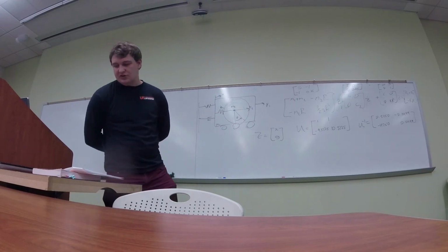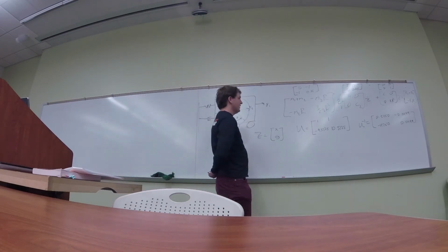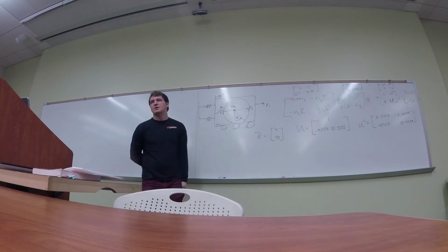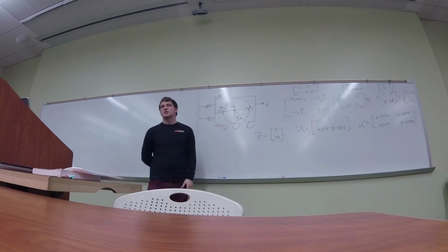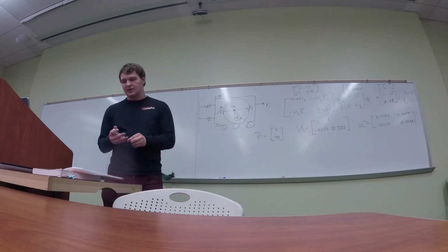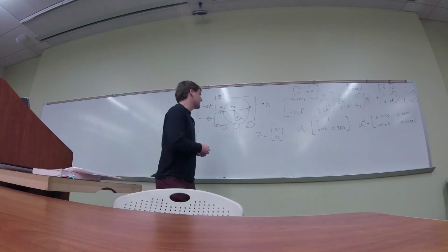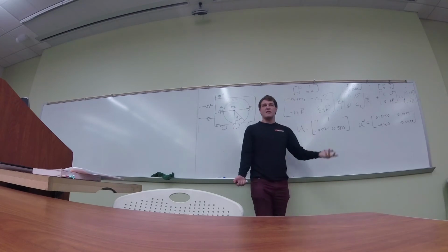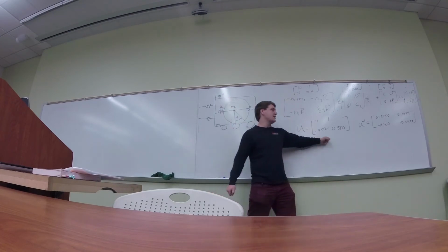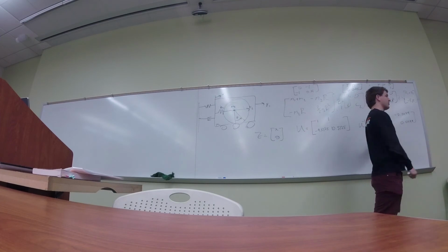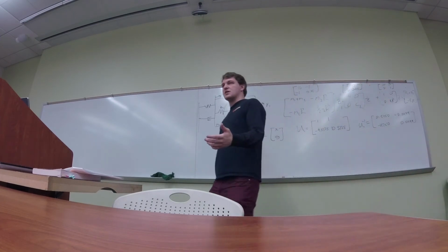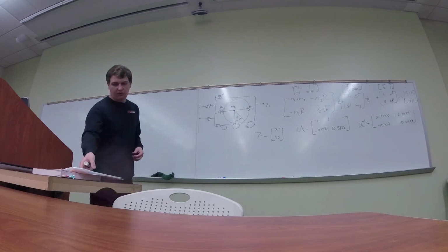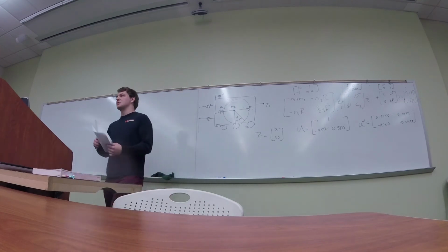Well, he gives you these equations, so what I'm assuming is it's some sort of friction of your roller or something. He's just saying there's damping associated with it. Because he literally says, here's your system, then he gives you this equation, he gives you the matrices, even though he just gave you all the masses and everything, so you plug those in, and then he gives you your modal matrix and the inverse of your modal matrix. So he's giving you quite a bit. And from there, the first question he asks is, let's find the modal mass, M tilde, K tilde, and C tilde.